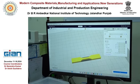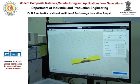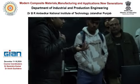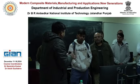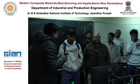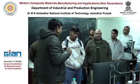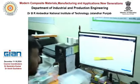process the STL file. What kind of processing will be required? See, I can print my STL file either in this orientation or in this orientation, right? By using my own knowledge, my wisdom, I will decide the orientation of the part. And how will I decide? Based on my requirement. What are my requirements? Whether I want to focus on the aesthetic look of the product or I want to focus on the strength of the product. Accordingly, I will select the orientation. So we will just change the orientation of this specimen first.